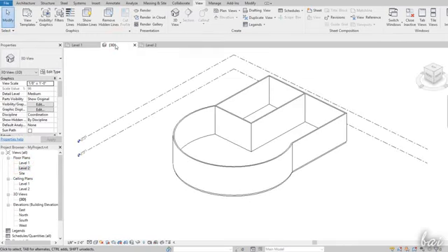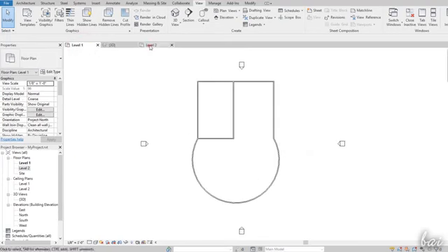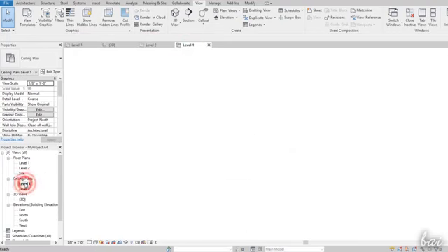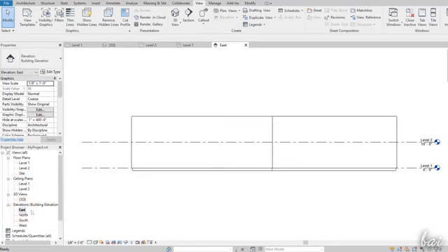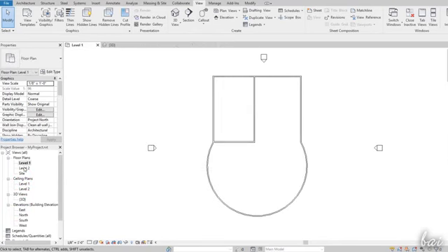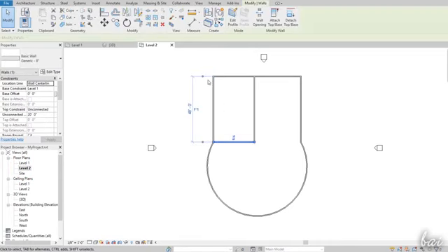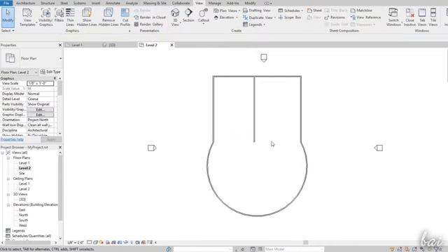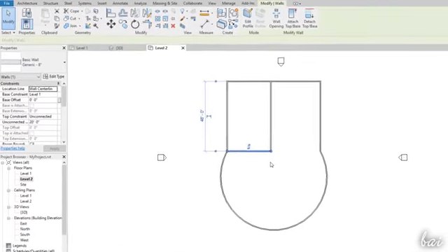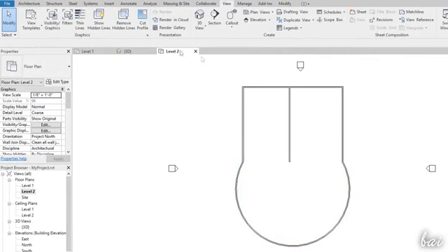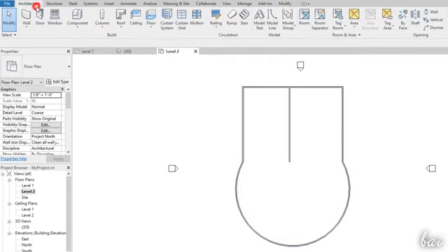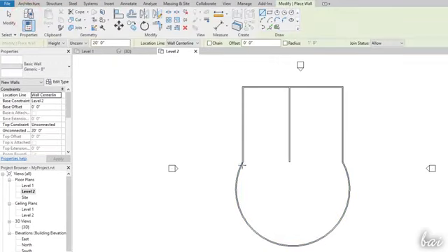Besides the 3D view, you have three kinds of 2D views: the floor plans, the ceiling plans, and the elevations. The floor plans show your project from top to bottom on a fixed height level, such as Level 1, the ground plane, and Level 2, 10 feet or 4,000 millimeters from the ground. These are used to drop all planar structures easier and also to fix the wall's base, which always follows the floor plan chosen.